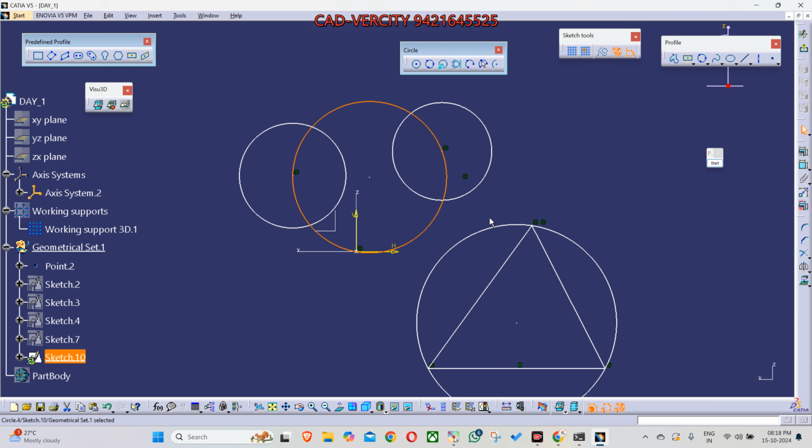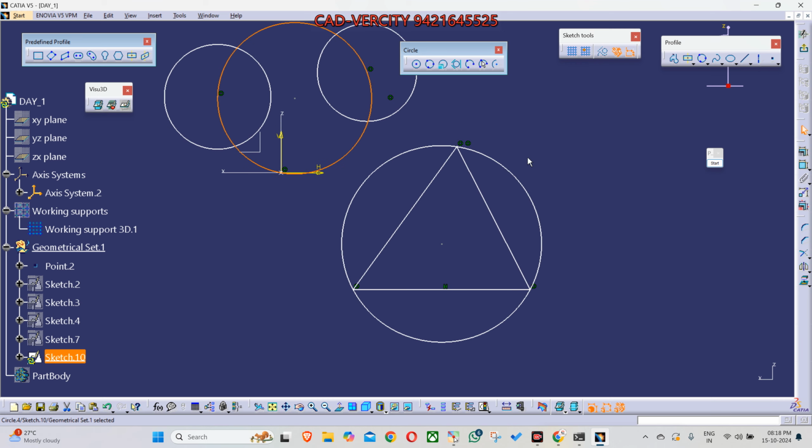So if I want a circle inside the triangle, who can tell me how to draw a circle inside the triangle? Just now we discussed tangent. Three tangent. Try tangent circle. Select this one. First line, second line, third line. Done. Can you see this icon? What we can say, the green two lines, tangent lines. This is a concept called tangent.